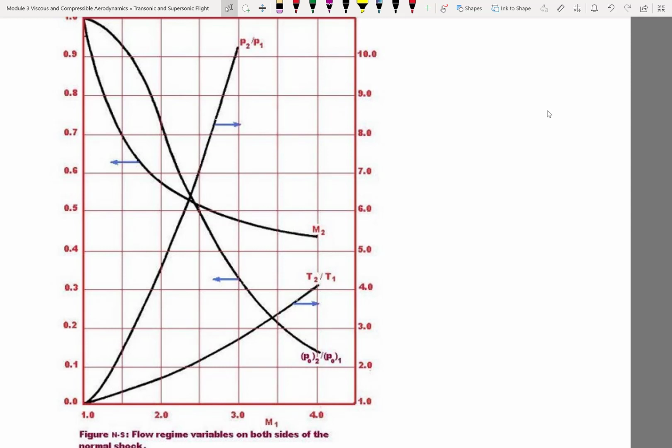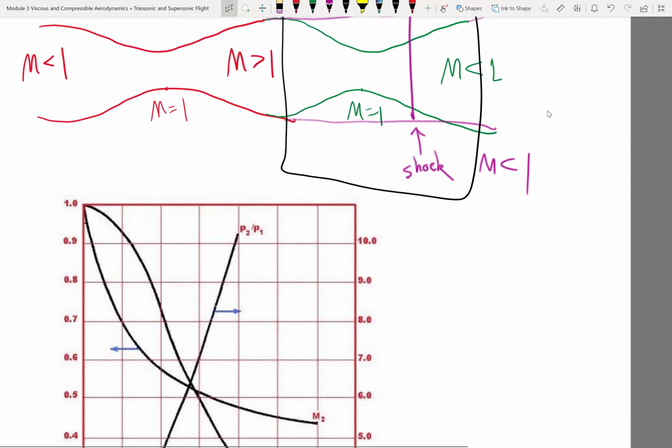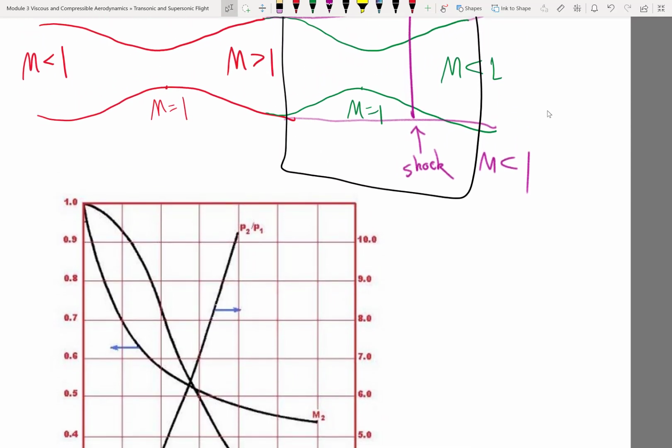It's basically when the stream tube decelerates to 0 velocity, what is the temperature of the fluid. So no matter if we're decelerating through the green case isentropically or through a shock, and then further we decelerate to zero velocity, because of conservation of energy, the stagnation temperature is the same. So if I draw an additional line over here, that'll be TT2 over TT1. It just stays as 1, doesn't change.